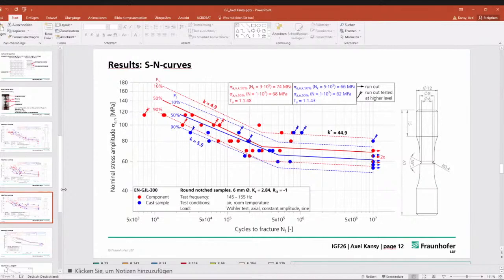You realize that with gray cast iron, sometimes components are machined and the sections have to be very, very thin. The differences in mechanical behavior are very high, so a model of the phenomena to bring into our software tool to design the components is important.